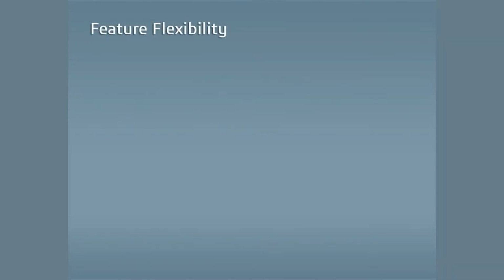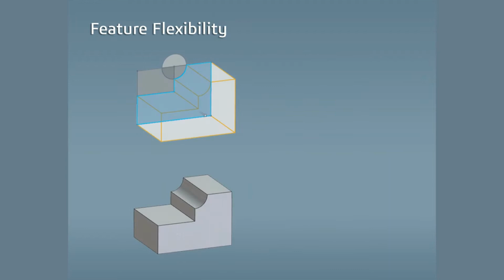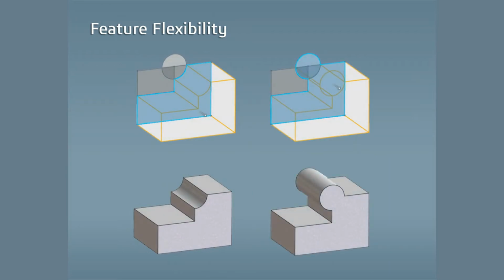xDesign provides a great amount of flexibility when working with sketches and 3D geometry in your model. Regions of a sketch can be used as the sketch profile for creating a 3D feature. This means you don't have to have a single closed profile, and at any time you can edit the command and add or remove other regions of that sketch to create the geometry you're looking for.